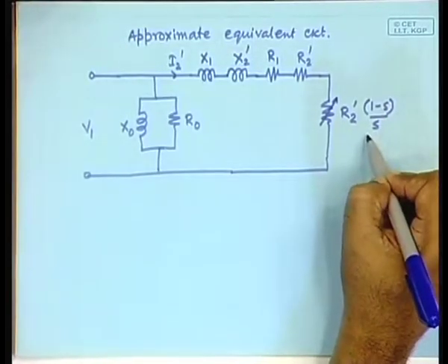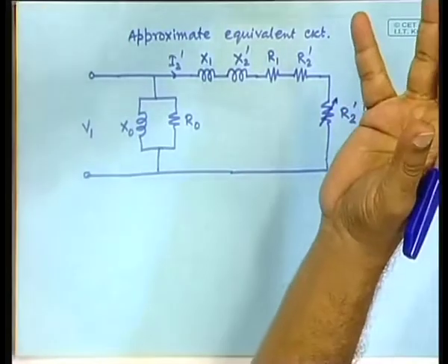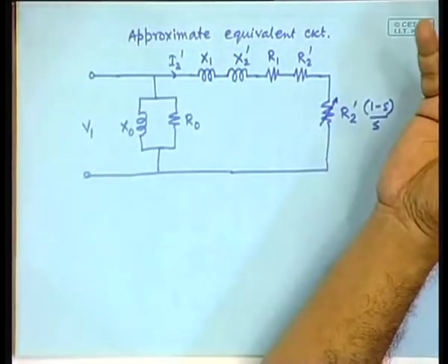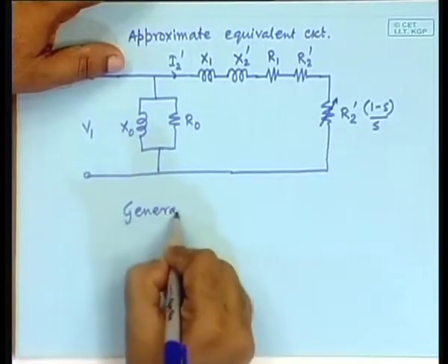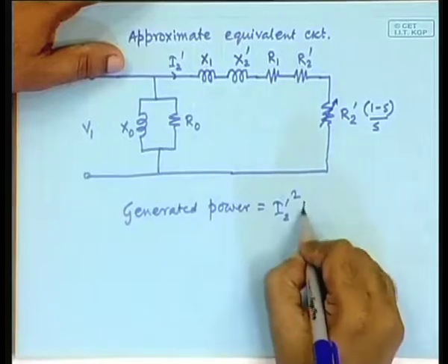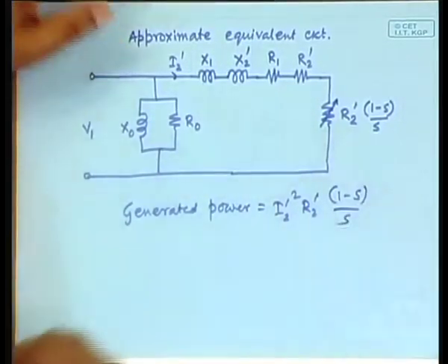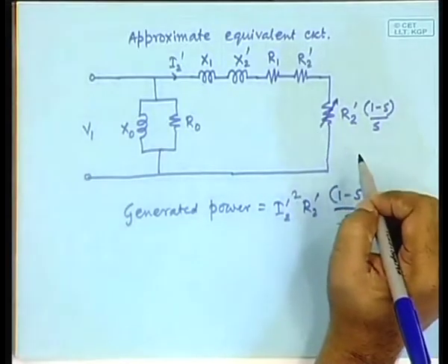So, the whole thing becomes a negative quantity, meaning the I square r loss is still I square r, right, but that I square r now becomes negative. I remains positive, but since this term has become negative, the I square r becomes negative. What is the physical meaning of a power being negative? It is generated power. So, the quantity of the generated power is again obtainable directly from the equivalent circuit, a simple affair. So, we find that this amount of electrical power will be generated.